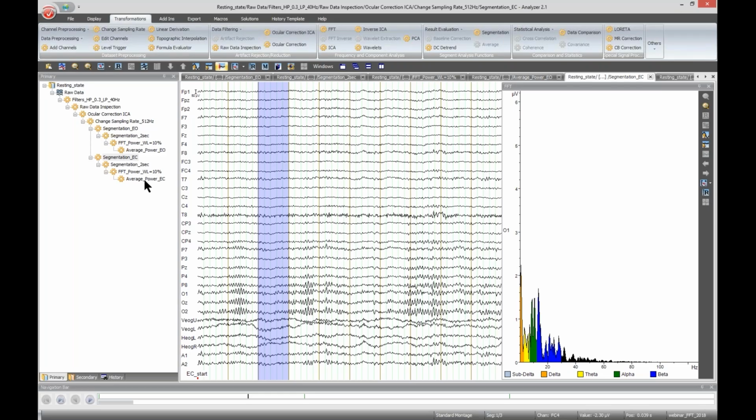When you window your data, the right and the left side of your portion of data will be dropped. In order to avoid loss of data, when you overlap your segments, you can still retain these portions of data. So for this reason, a sliding window is of advantage.